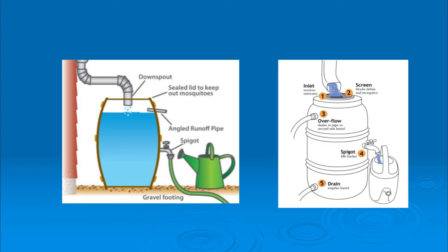So again, say we were down to 320 gallons or something in a 1/4 inch rainstorm, and you have a rain barrel at all four corners of your house, or at least you have downspouts at all four corners. So we split that and say it's 85 gallons. Well, a rain barrel at 50 gallons is going to be full in a 1/4 inch rainstorm. So just take that into consideration when you think about how you're going to use your rain barrel and where you might want to place it.